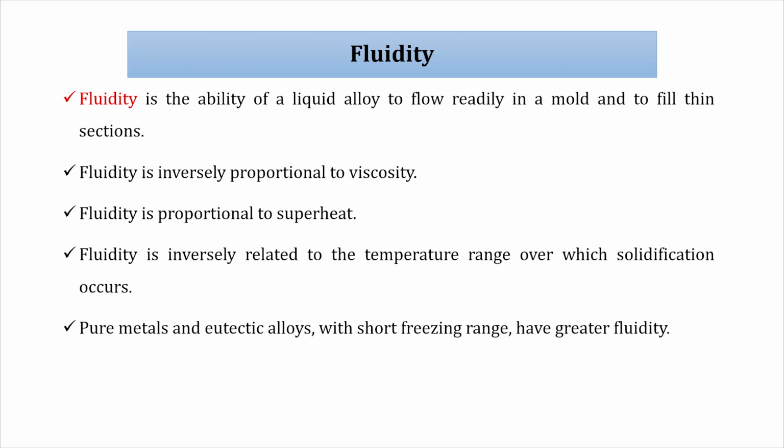Fluidity is inversely proportional to viscosity. If high viscous, low fluidity; if low viscous, high fluidity. Fluidity is proportional to superheat.